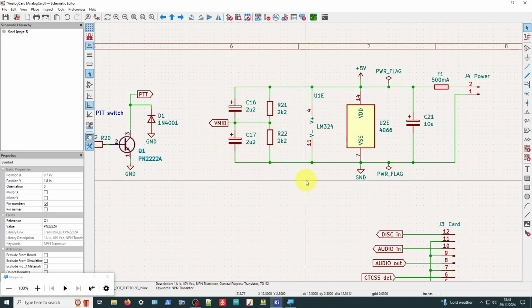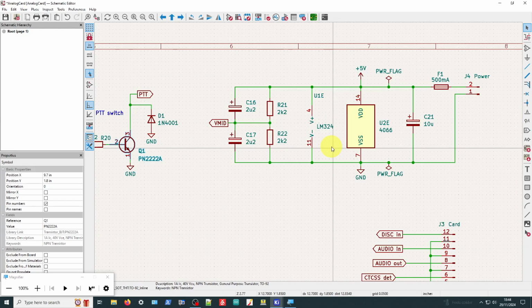They can be ceramics. So sticking completely with multi-layer ceramics, just because they're very easy to work with. Obviously they're non-polarized, you can stick them in any which way around you like. It's less to go wrong, and they're also a bit more reliable as well, with a better ESR generally.